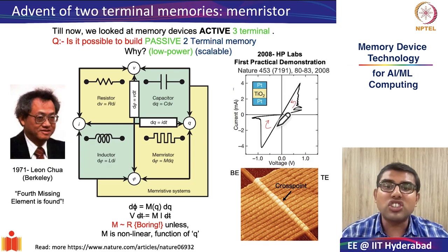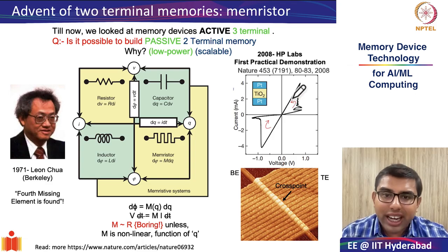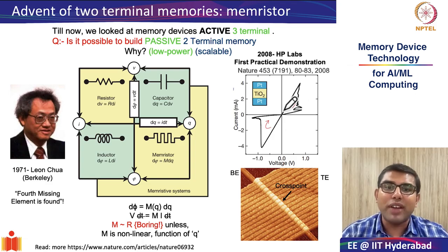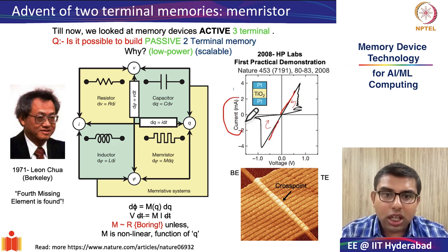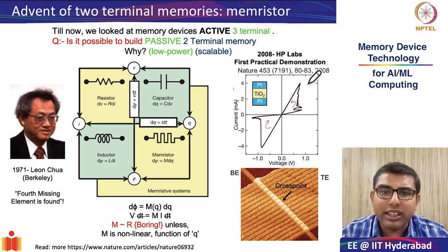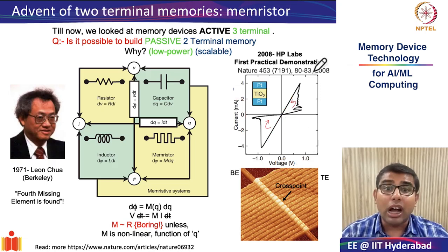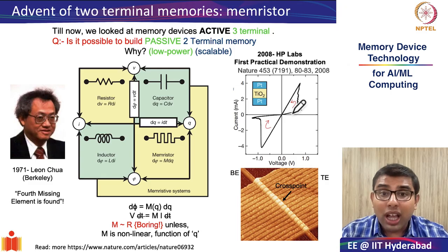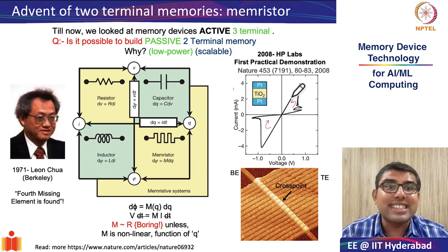How can we say this is a memristor? You see, it shows very simple resistive behavior. In this curve and in this curve, we see that the current is proportional to the applied voltage, roughly linear, mostly looking like Ohm's law. However, there is also a very interesting thing called hysteresis.